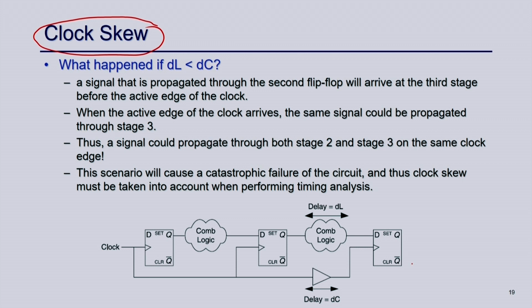If it happens, there is no problem, but in reality that may not happen because of some delay, as we discussed about clock gating. Even the clock path has to be routed through some layout. So, it may not happen that the clock actually reaches all the registers at the same point of time.